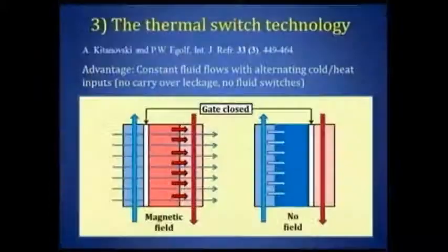So by this, we had the following idea. Instead of turning, we built a machine with layers of magnetocaloric material. On the left-hand side, red in the middle, this layer, that's magnetocaloric material. And we built heat gates to the left and right. And by this, we just can flow by with a cold and a hot flow, maybe countercurrent. And then we just switch open, closed, alternatively on the left and right side. And by this, everything also works, and we don't have these limits in frequency.